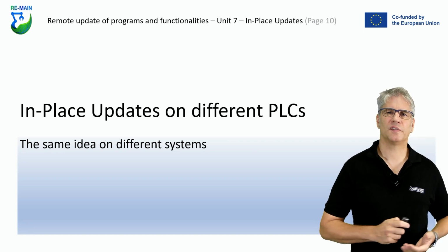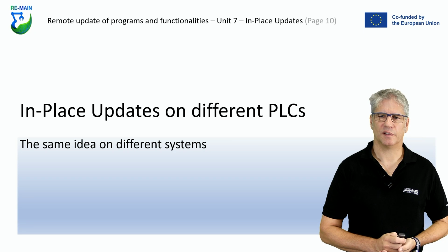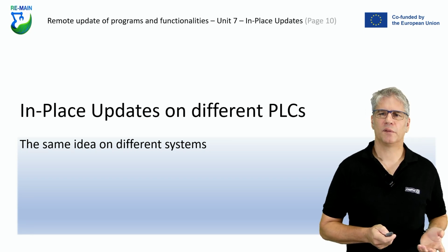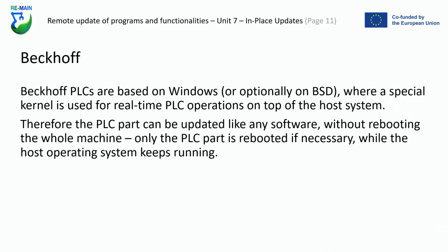So how do these in-place updates look on different PLCs? It's the same idea, but on different systems. Let's start with Beckhoff. The idea of Beckhoff PLCs is that you have a Windows operating system, and this gets hardened real-time components that run within Windows, but without needing Windows at all. Which means that even if Windows crashes, the real-time PLC process does not crash.